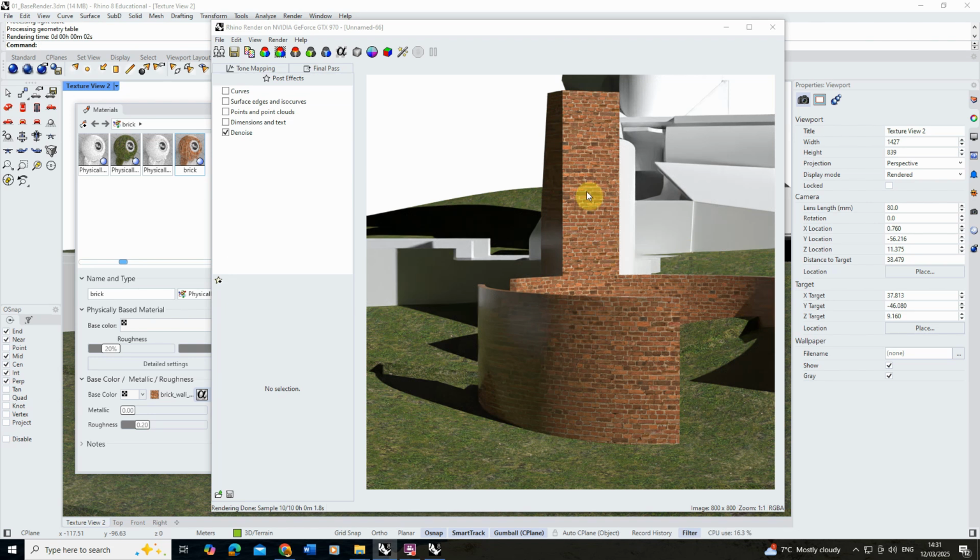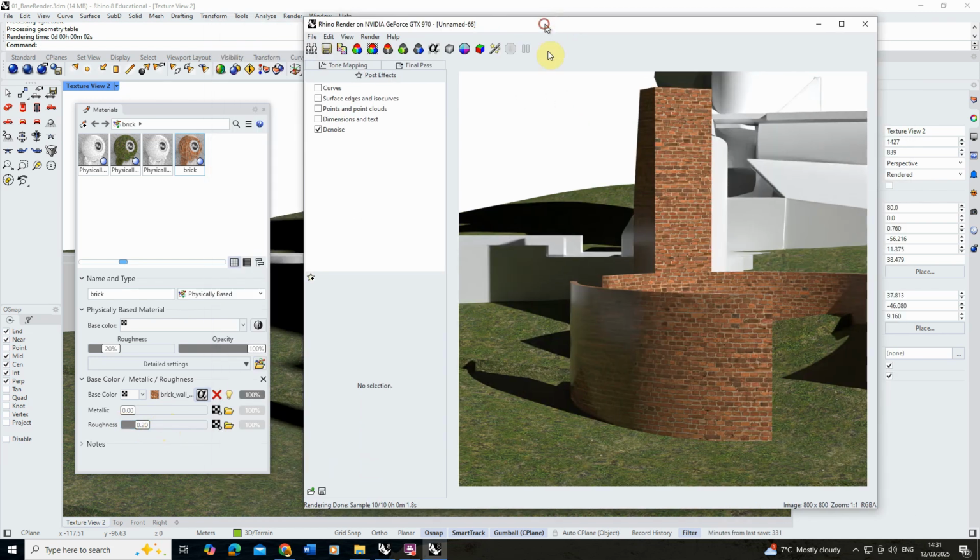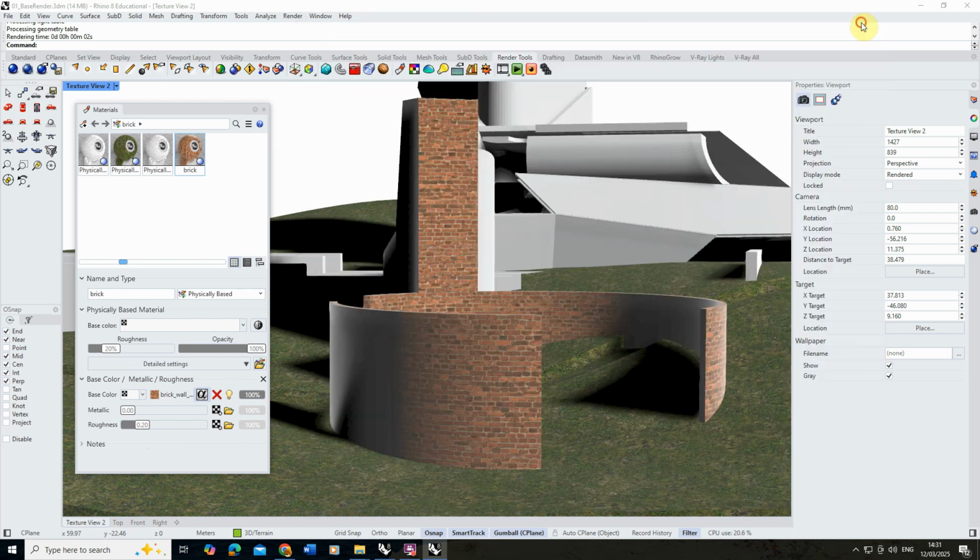The colour's a little bit more vivid, but we still have this sort of shininess to it, and that's because we haven't actually changed the roughness of my material. It's really just set to the original roughness setting, which is giving it that shininess. So in order to take away that, we need to also add a map into that roughness panel.